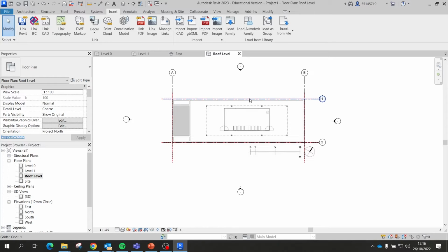Yeah, the view range. So the view range, why is that happening? The reason why this is happening, so I can't see below level, in this case, this is the roof level, level 2, whatever. The reason why it's happening is because I created a new level. I didn't copy a level they already have. I'm pretty sure, 100% in my mind at least. If you just copy what you already have as a level, that'll be fine. You'll be able to show the grid below.